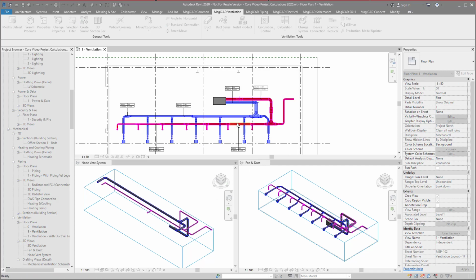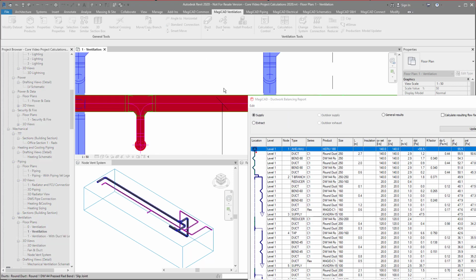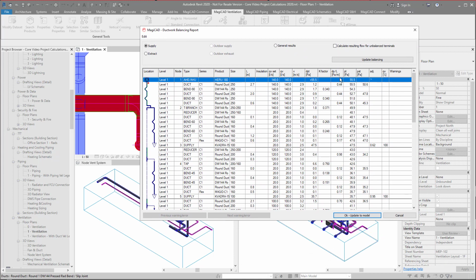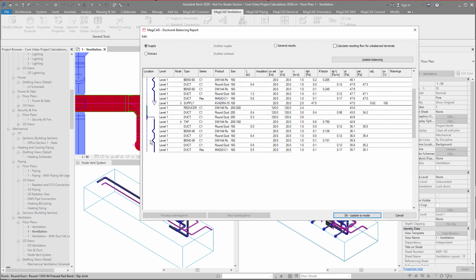And once we select the system we want to size, this will size everything that's connected to that. As you can see, we've got a fan here. So we've got two systems applying extract on there. And within this report, we'll get down the left hand side the simple schematic with the index run highlighted in green, but we'll also have all the different criteria: flow, K factors, pressure drops, static pressure is even in there, and even series and sizes.